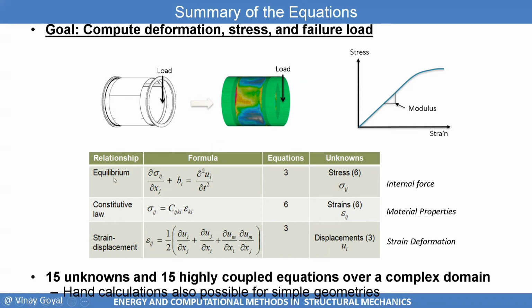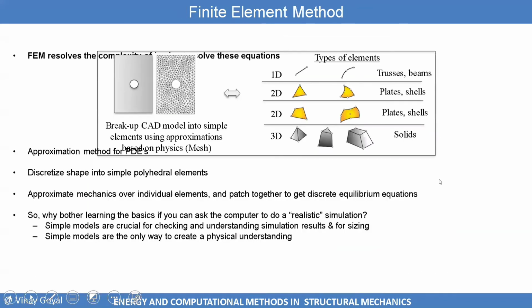I have equilibrium equations, constitutive law, and strain-displacement relationships, nonlinear in this case, where I included higher order terms. The derivative of W with respect to epsilon ij could be fully nonlinear but reversible. There are 6 strain-displacement relationships, and you have to solve all these equations together, and that can be very complex.